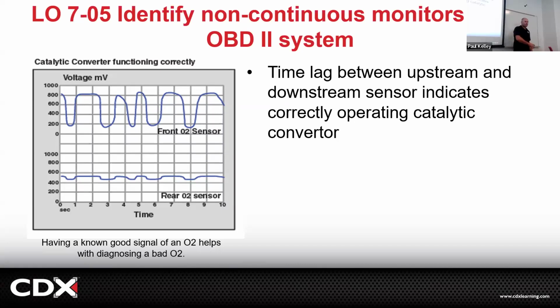And then it once again starts looking at the sensor, and it sees the result, right? It's like leaning way out. And then it's like, okay, whoa, that's enough. That's too lean now. What should we do to get it off of too lean and back to normal or rich? Add more, boom, and it does it, right? So it's this cycle. The input is the sensor. The output is the injector. The PCM is obviously getting information and giving a command, right? So that's what it does.